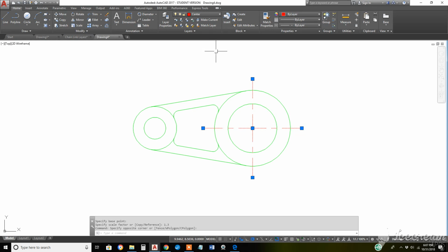Yep, sure enough, this line, we got a big cross instead of a little cross, so let's move it from the center layer to the center X2 layer. Now remember, center X2 is for big circles, and this circle's big, so it'll look good on center X2. Hit escape to deselect objects.